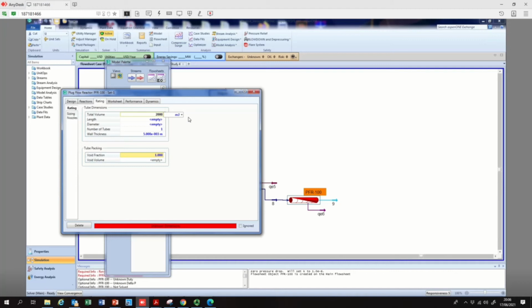So let's assume diameter is equal to 11. But at the end of the day, we are going to change it. What the literature says is that the residence time should be roughly around 0.09 hours, and the length to diameter ratio should be equal to 1.5. So these are the industrial conditions. This one we took from the literature, from the work of Lakshmanan et al.